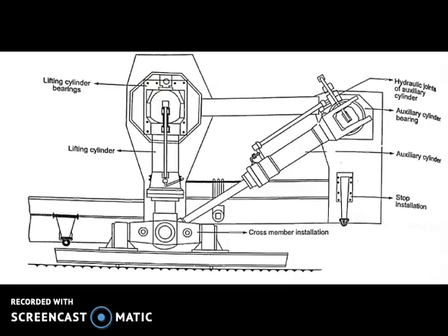And the next type is the hydraulic ram type. The hydraulic ram type system utilizes the advantage of hydraulic mechanism in operating the working of shoes. They consist of four hydraulic cylinders attached to the revolving unit of the dragline. The pistons along with the rods are mounted on ball joints, which are capable of sliding over the slides placed on the shoes. There are two push cylinders placed on either side of the revolving unit of the dragline. The pistons and their rods are provided on pin points in the shoe.